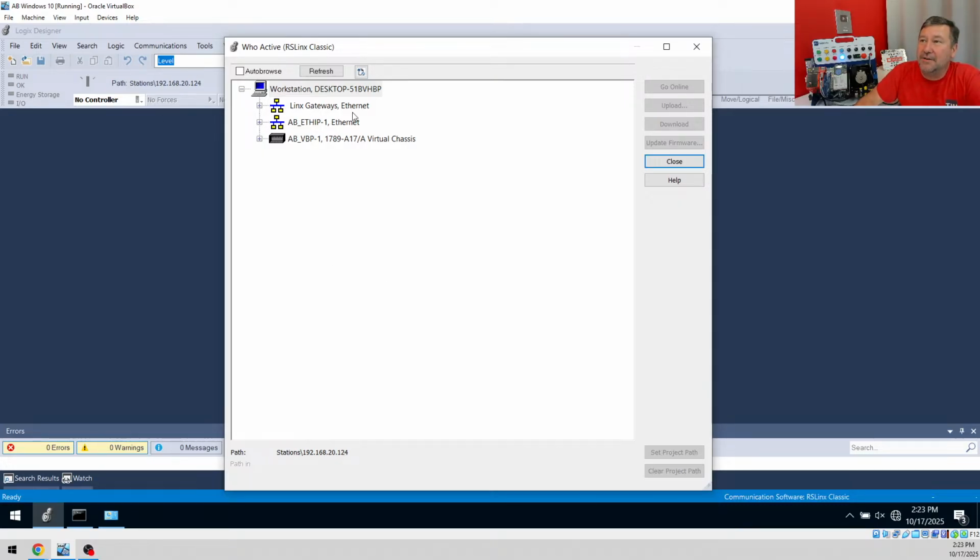And here is probably the Achilles heel I always felt of RsLinx Classic. Oops, let me check that box. That's not normally unchecked. By default, when you installed RsLinx, the only driver that was actually configured was Linx Gateway via Ethernet. And there's only one worthless thing in all of RsLinx, and that's called Linx Gateway via Ethernet.